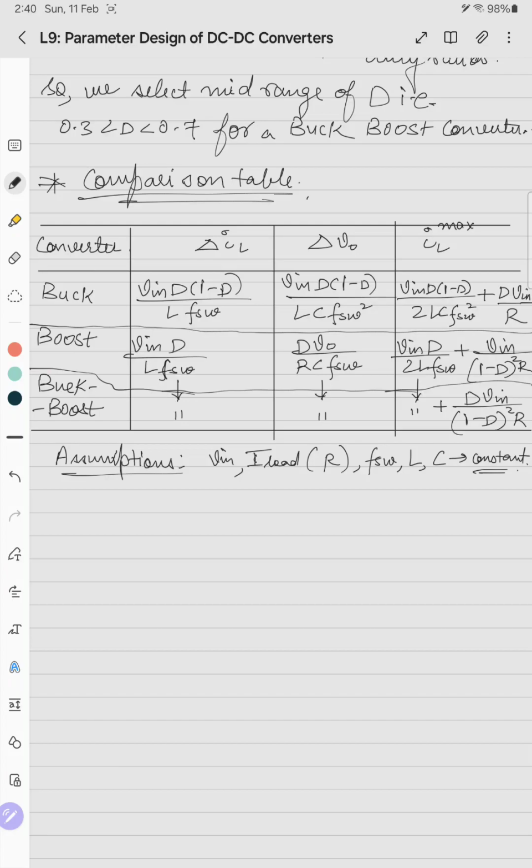The reluctance of the coil you can set by using the ferrite core material. The choice of the ferrite core material also decides the peak flux density B. And for the same given number of turns, if you want to increase the inductance, that is decrease the reluctance, you can introduce an air gap in it. So these are the multiple factors in designing an inductor, and one of the important factors is the peak inductor current.